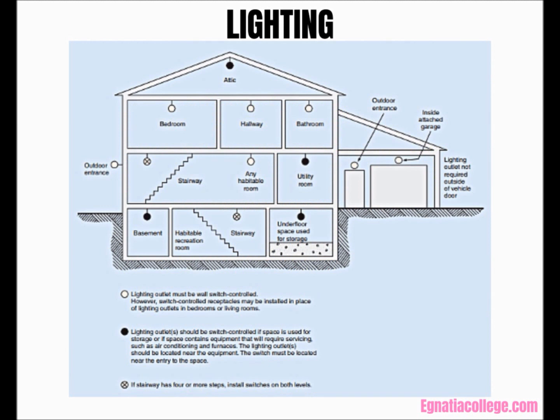The provisions for supplying a light fixture in a room or area and whether it is to be controlled by a wall switch are found in Part 9 of the National Building Code of Canada. The CEC has adopted these requirements, which are found in Rules 30-500 through 30-510. It outlines these requirements for lighting in dwelling units. This Figure 4.1 shows them graphically.